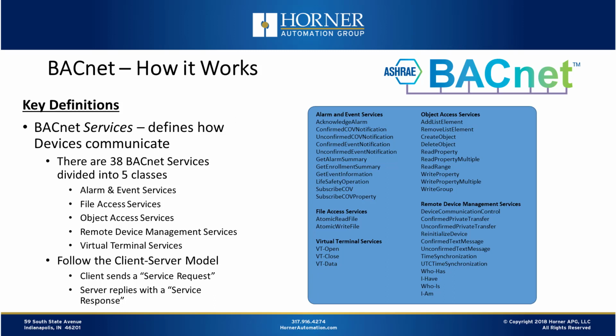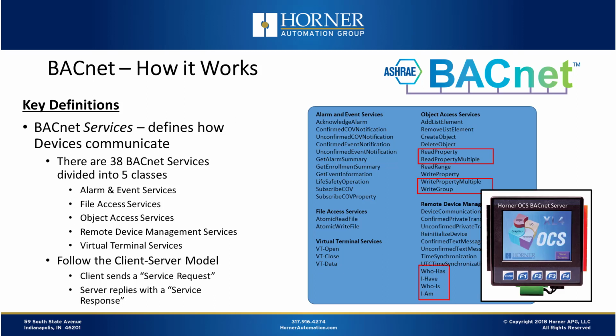And then services within BACnet follow the client-server approach. So one device, the client in the transaction, would send a service request, and then the server, which is the other device in the transaction, is going to send a service response. From a Horner standpoint, we just quickly have highlighted there the services that we support as part of our BACnet interface.